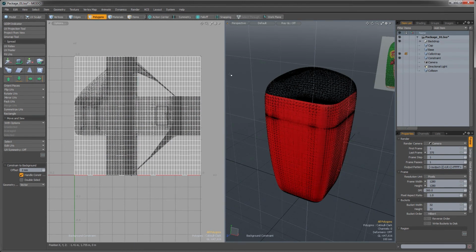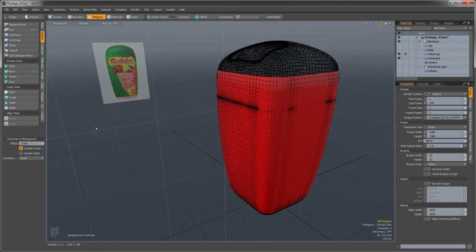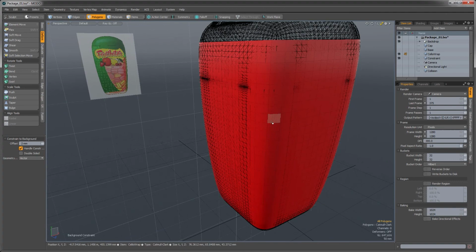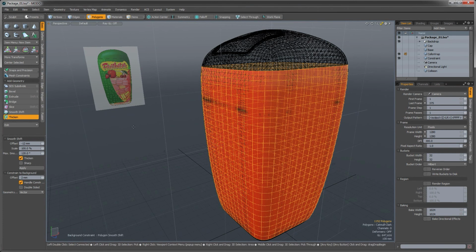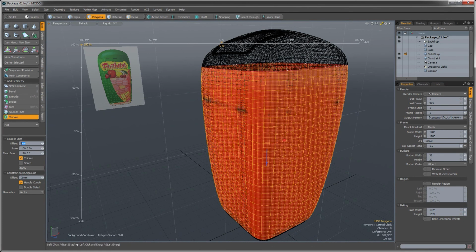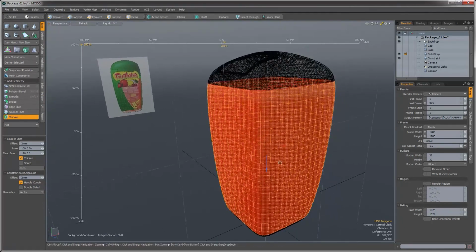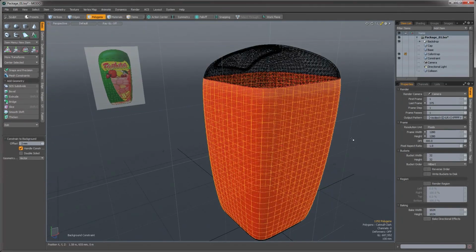So now the one last operation we're going to do here in model is we're going to thicken this guy. We're going to make this actual geometry that's going to have a front and back face with thickness. So it's going to basic and thicken. Click in there, and we're only going to thicken this 2 millimeters because it's a very thin little cellophane wrapping for the outside edge.